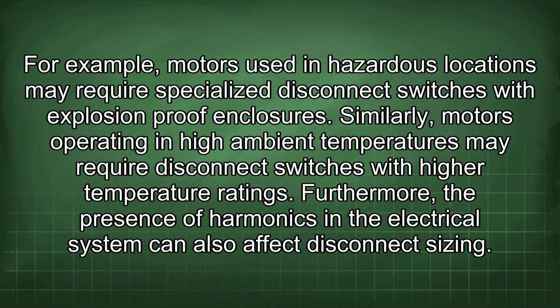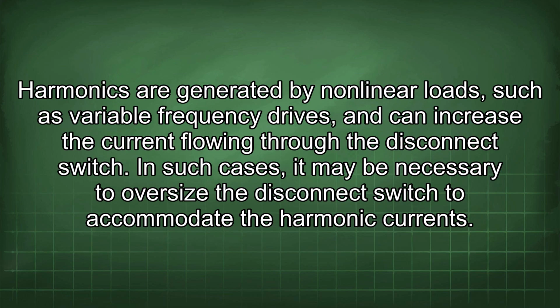Furthermore, the presence of harmonics in the electrical system can also affect disconnect sizing. Harmonics are generated by nonlinear loads such as variable frequency drives and can increase the current flowing through the disconnect switch. In such cases, it may be necessary to oversize the disconnect switch to accommodate the harmonic currents.